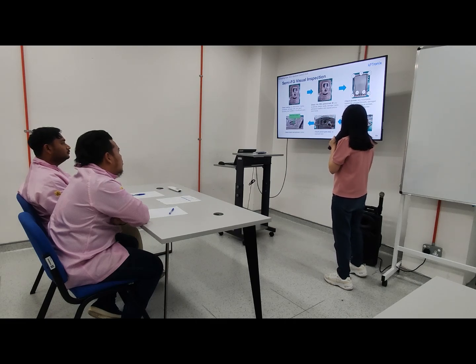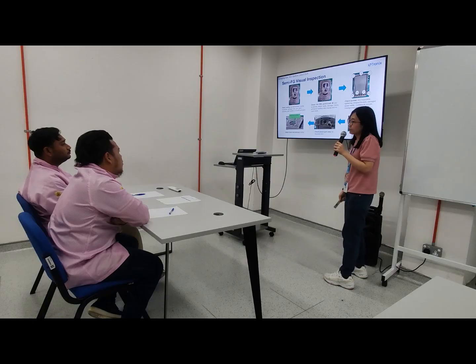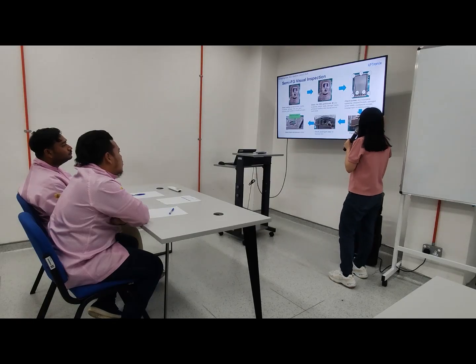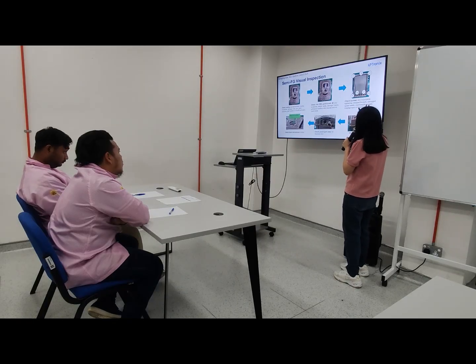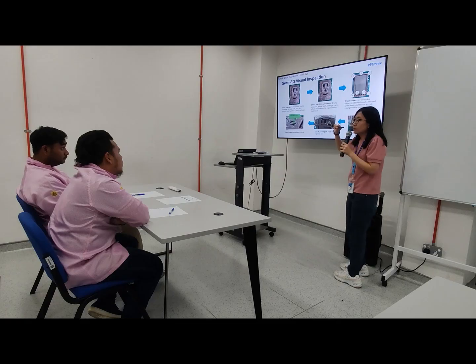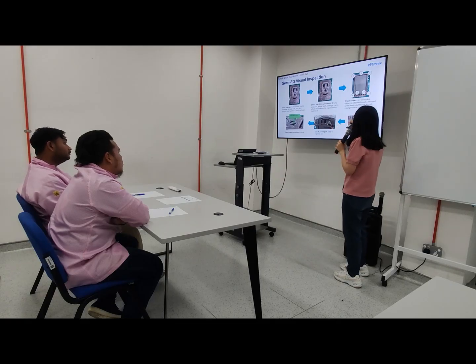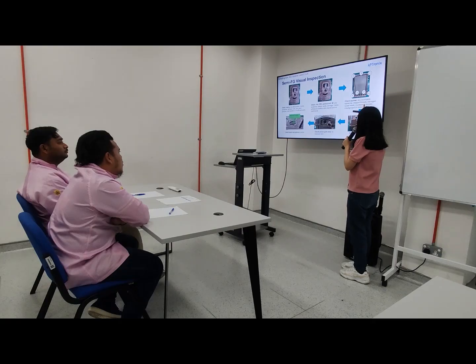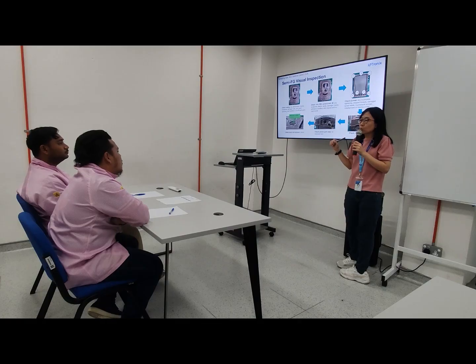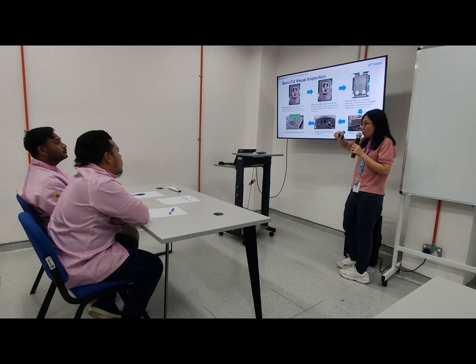After the third step, we go on to screw checking. For screws, it depends on the model. For this model, we have 7 screws. We check for any incomplete patterning, stripped or damaged screw heads, countersink screws, misaligned or mixed screws. Most important, the correct screw, and that the screwing is totally complete and fits properly.